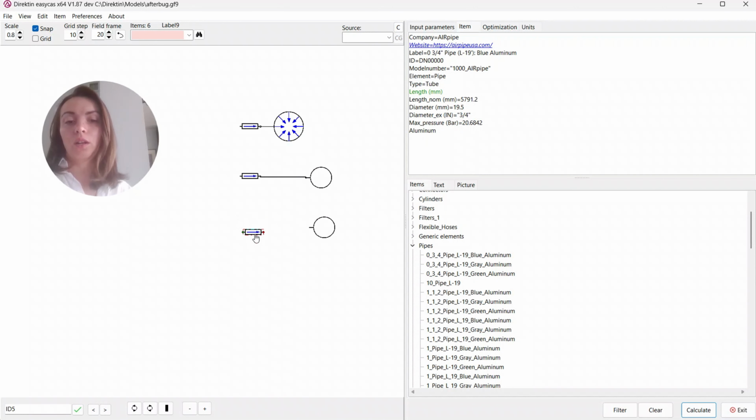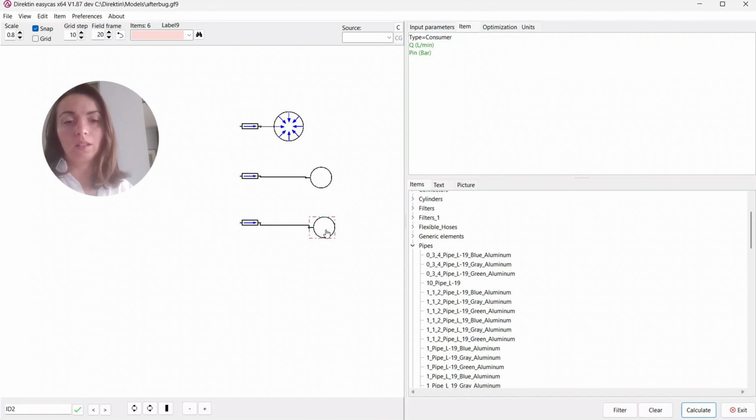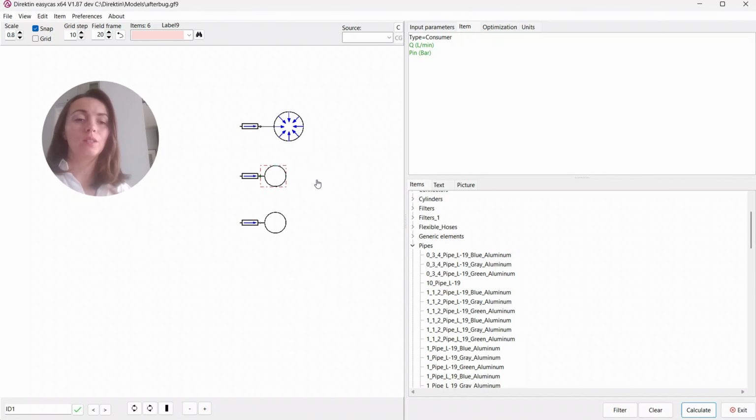So meaning that if you have more valves, filters or regulators, yes, those are components that will cause pressure drops and changes in your system, but you can start from the overall design, so meaning from the simple design, and then going into the details with time. So you can refine your design by adding more and more components, air tanks, filters, dryers, and so on.